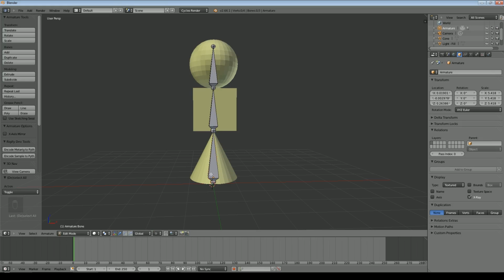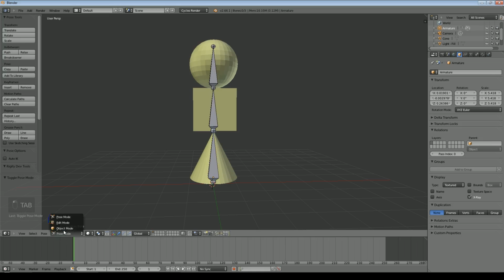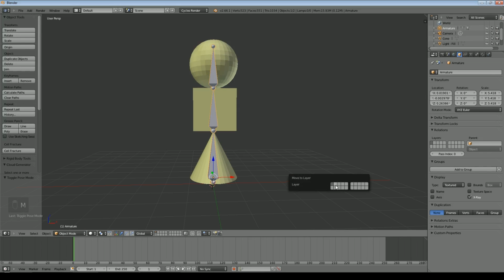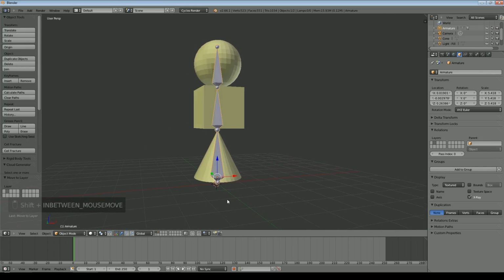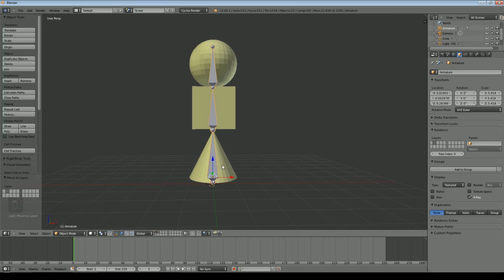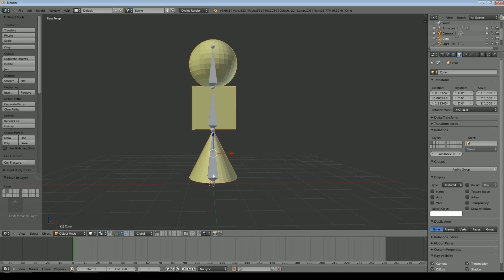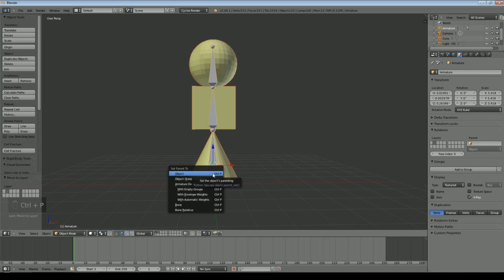Before I do that though, what I'm going to do is move that to another layer because it makes it a bit easier to work with. So there's the bone and there's the object, and then I click, holding shift down, I'll click here, and that basically displays both layers at once. Next thing I'm going to do, select my object, then select the bone, Control P, and you get more parenting options than normal. And I'm now going to say armature deform with automatic weight. So I'm parenting, that's what Control P does, but I'm adding effectively an armature with automatic weights.